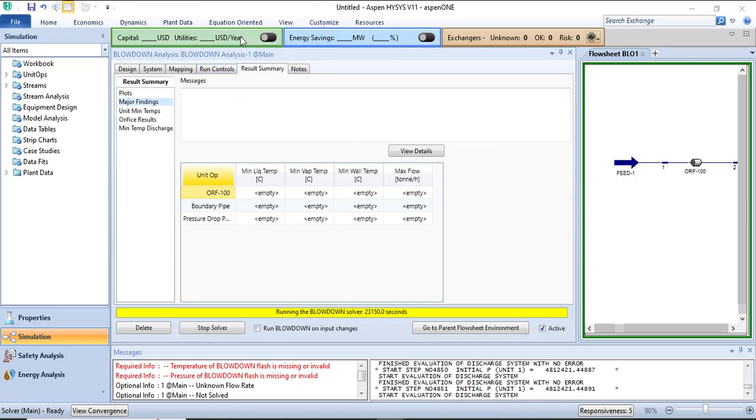So guys, the pipeline pressurization is running, and we'll see the results once it finishes. The blowdown calculation has been successfully completed. But the thing is that we weren't able to reach that 90 bar pressure. So either we have to increase the time and the flow rate, and let's just show the plots.